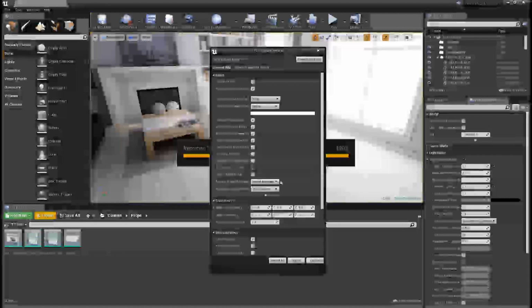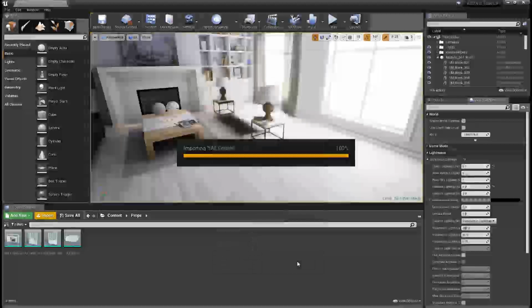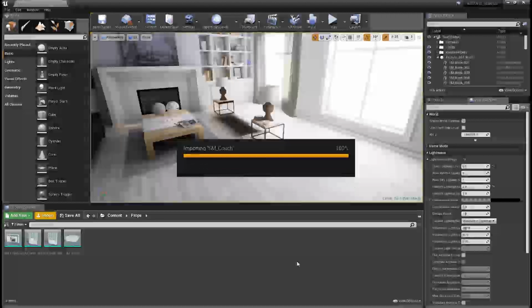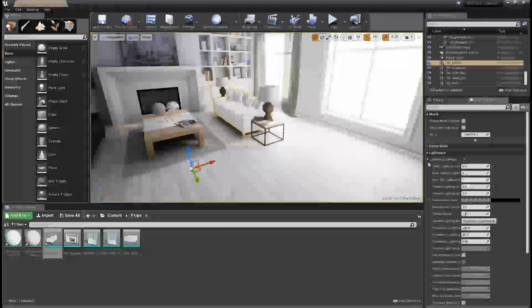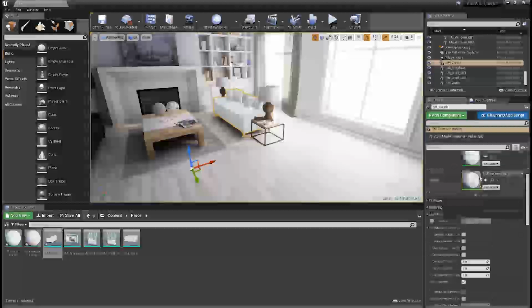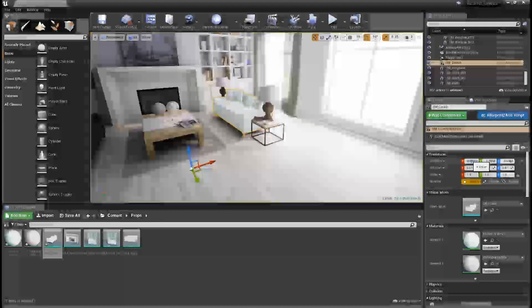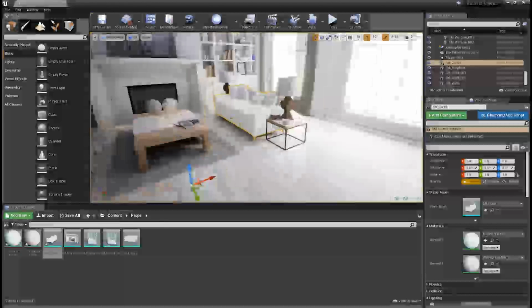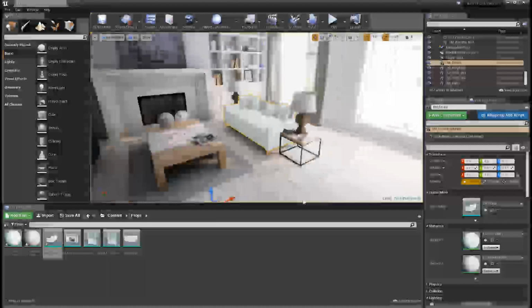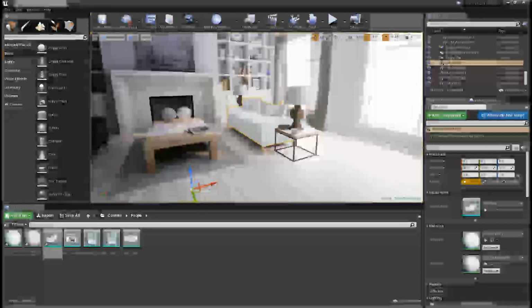When exporting with EpiX, the assets won't be in your Unreal level already, and you'll have to drag them into the scene one at a time. But if you've used this technique, the assets will be positioned in the same location they were in the 3D tool, without needing to manually be moved or rotated. Of course, you'll have to make sure that they're all positioned at 0, 0, 0. It really depends on how you want to work.